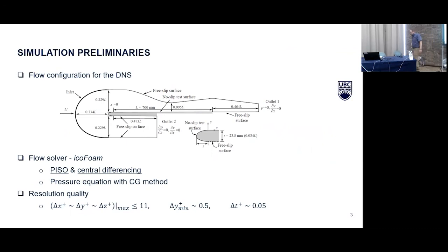But the numerical noise is not much larger than machine zero. So it's not really what's responsible for triggering the transition process. The transition is being triggered, in my understanding, by this interaction between viscous and inviscid instabilities of the laminar separation bubble. So no imposed free stream turbulence.